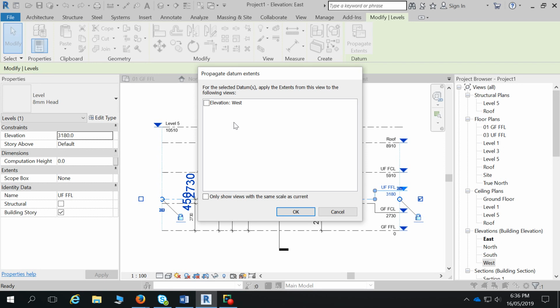So instead of having to do the break elbow 4 times in each elevation, you only have to do it twice. It also means it copies the same break across the 2 elevations, rather than it being slightly different if you do it differently on different ones.